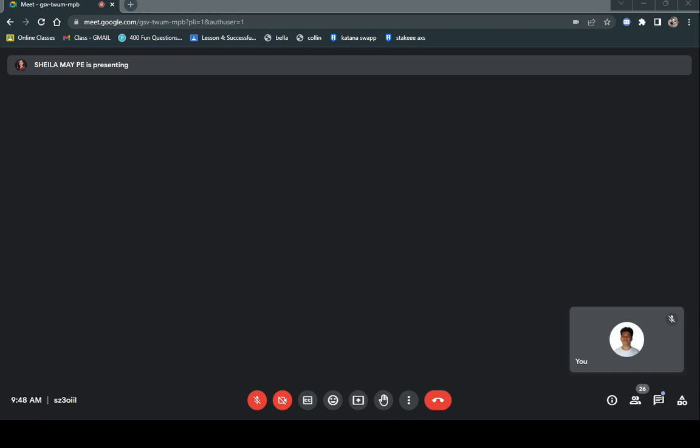But VGS is VG, which is 2.16, minus ID times RS. We don't have ID. RS is 1,100.